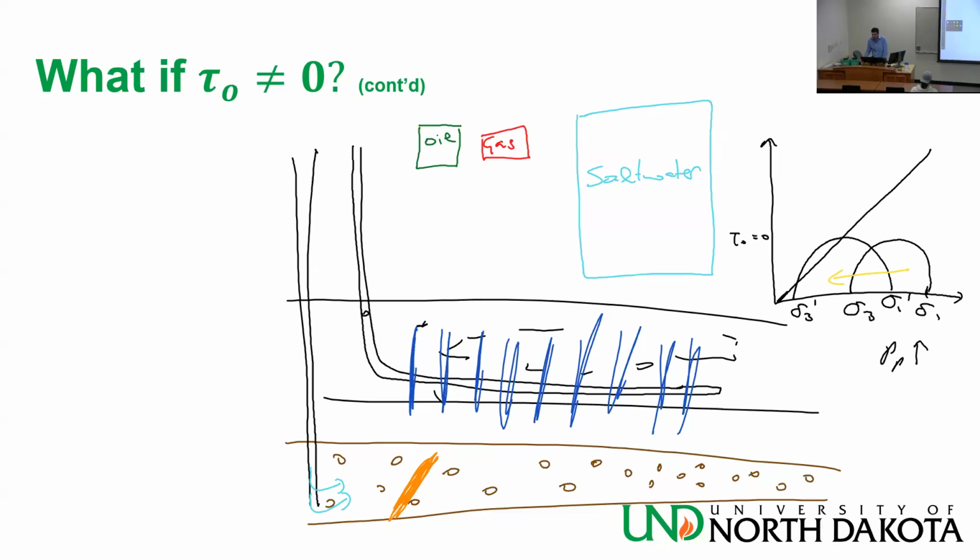For the tensile failure, we're not going to do it in this class, but you need to look at the negative side of the Mohr-Coulomb diagram. You need to look here for the tensile failure. But whatever we use the Mohr circle diagram for is shear failure, because it's shear stress versus normal stress.